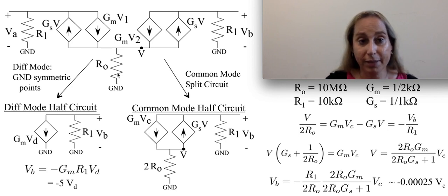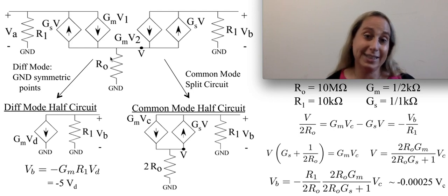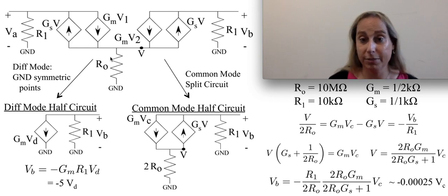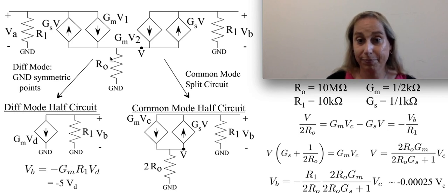So that means I can talk about a whole circuit on the one side and a whole circuit on the other. Well, remember what we're doing with these differential circuits is applying two inputs, which in this case are V1 and V2. I'm going to be applying the same voltage to them, and then I'm also going to be applying a voltage that's moving opposite to each other. So a common mode, or a sort of average, where everybody's at the same voltage, and then one where everything is completely different around some sort of DC level.